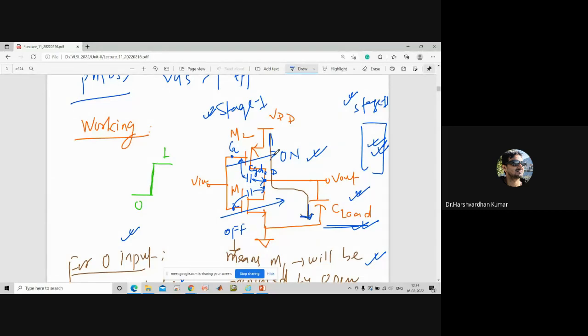Or if you change the aspect ratio of NMOS, you also get the same logic at the output. So the change in aspect ratio is not going to change your output signal. This is the meaning of ratio-less logic level in static mode operation.